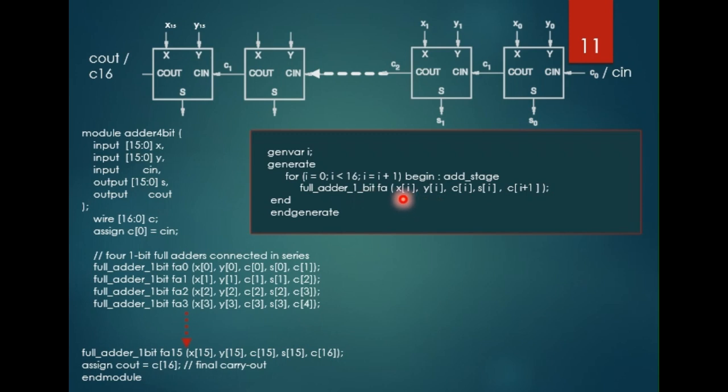And you utilize the iterator i to describe the top level signals. Now you see the reason why, when we declare the input, output and even the wire, we want the signal to be in vector or iterative form, so that we can use this array way to describe the one-line full adder here using iterator i.